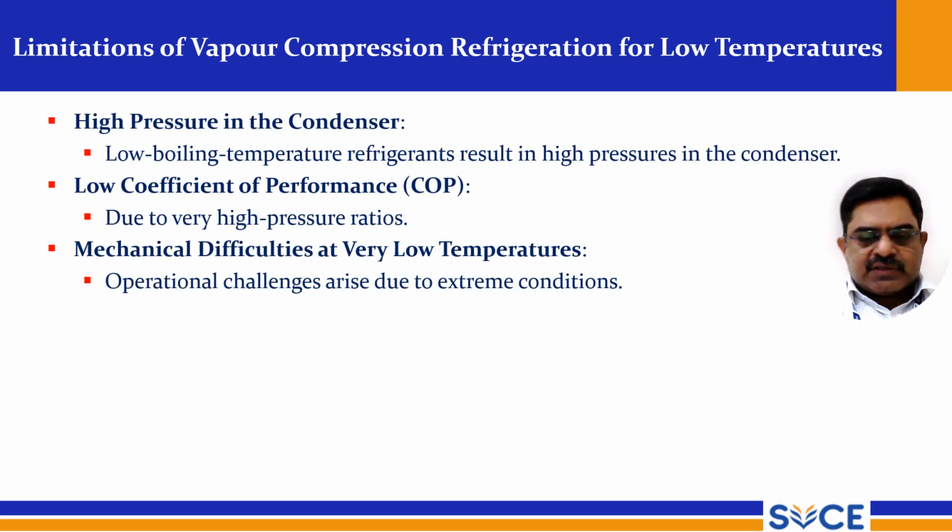High pressure in the condenser. Low boiling temperature refrigerants result in high pressures in the condenser. Low coefficient of performance, that is COP. This is due to very high pressure ratios, that is condenser pressure to evaporator pressure.